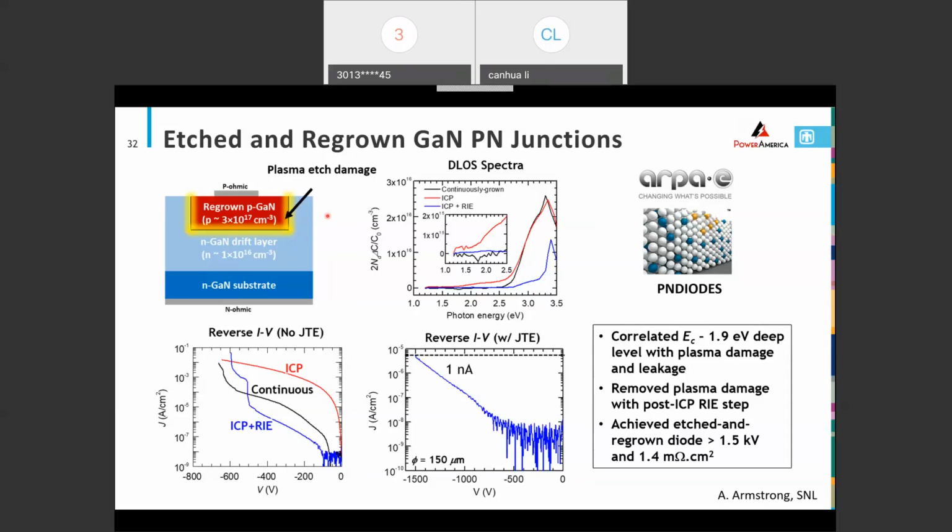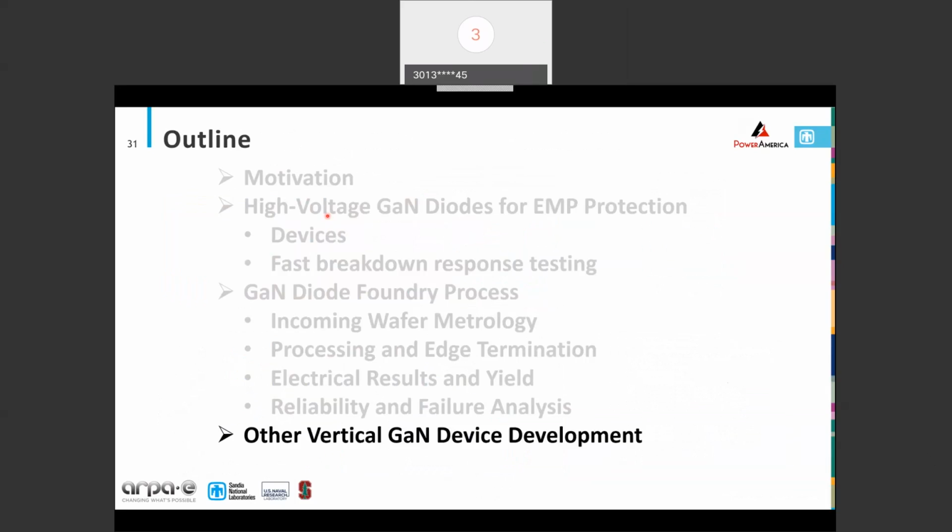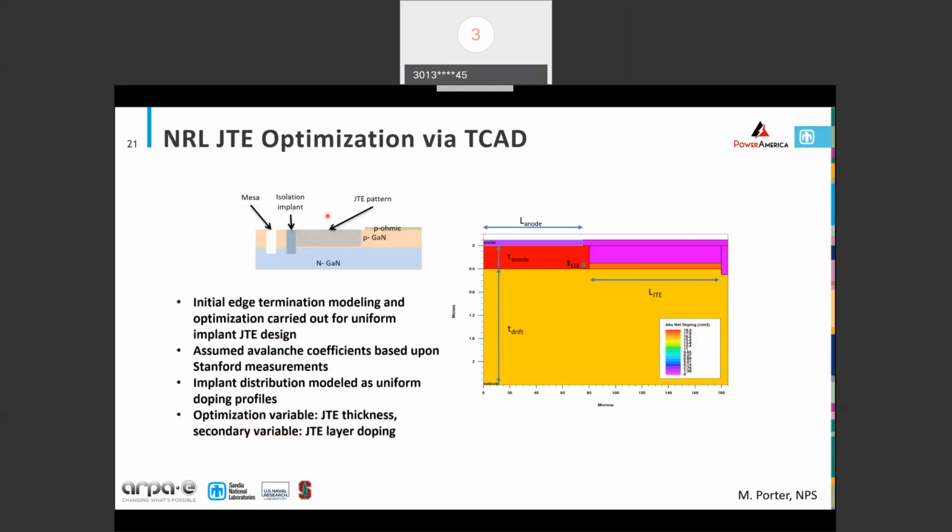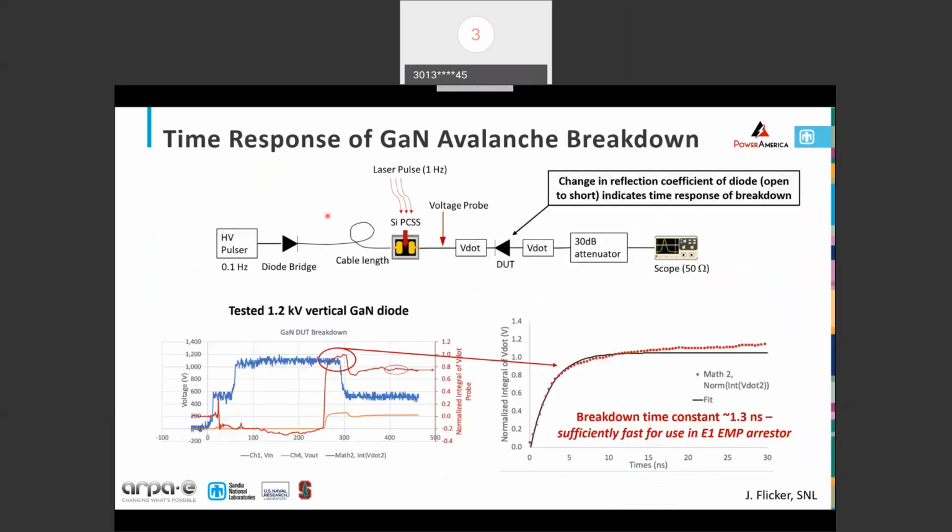Should one expect significant differences in reverse recovery behavior of GaN pin diodes compared to silicon or SiC pin diodes? Right. So maybe I'll go back to this slide. This particular set of data is for time dependence of reverse breakdown, but this system was actually modified from one where we measured reverse recovery. So we went from a forward to a reverse state rather than from a reverse blocking to reverse conducting.